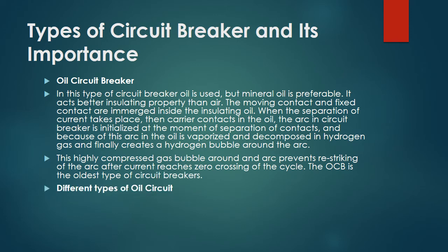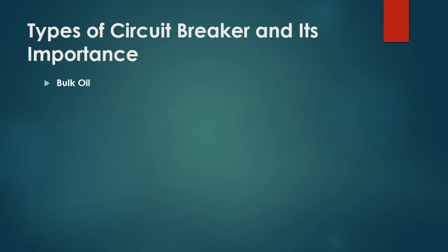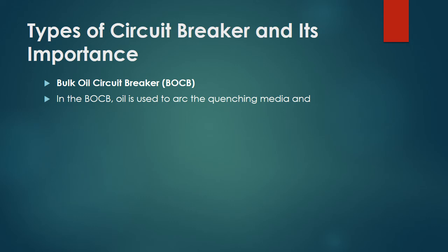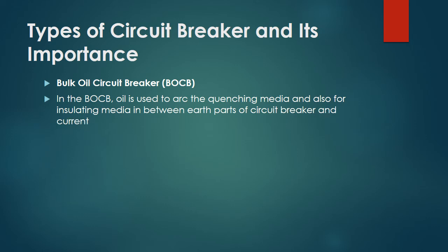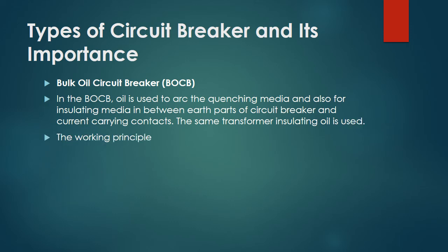Advantages: good cooling property because of decomposition. Oil has high dielectric strength. It acts like an insulator between earth and live parts. The oil used here will absorb arc energy while decomposing. Disadvantages: it will not permit high speed of interruption. It takes long arcing time.